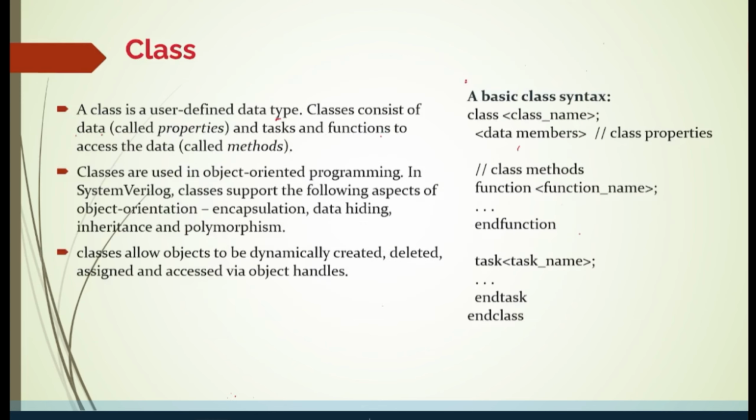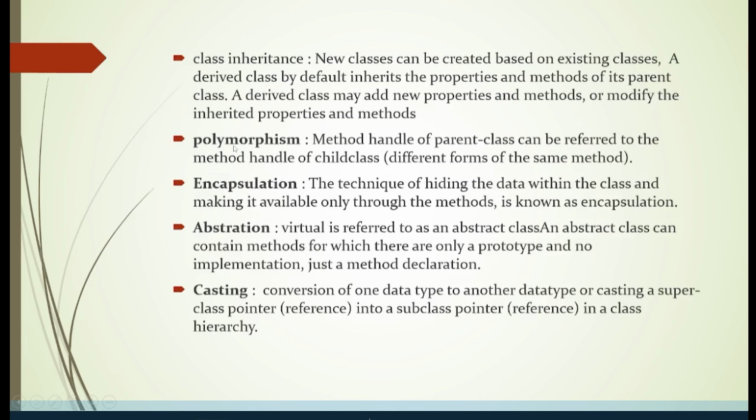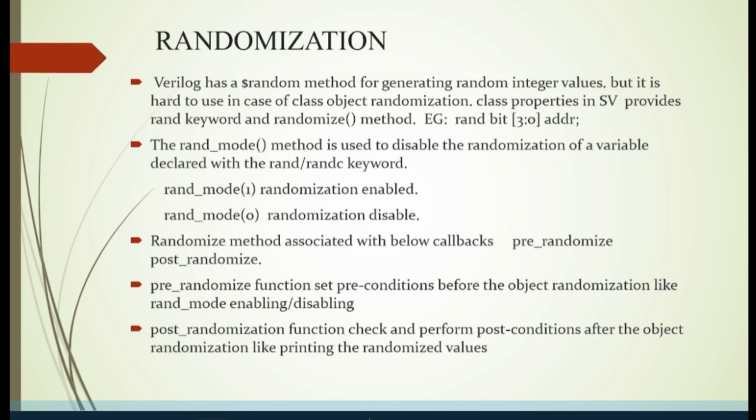If you see the test bench architecture we talked about just before, every component like generator, driver, monitor, scoreboard is class based. That means everything can be reusable, every piece of code can be reusable. Because of that, we save a lot of time in creating new code. Since classes are dynamic in nature, mostly we will adopt classes rather than modules in SystemVerilog. And then coming to the second important feature in SystemVerilog, which is randomization.